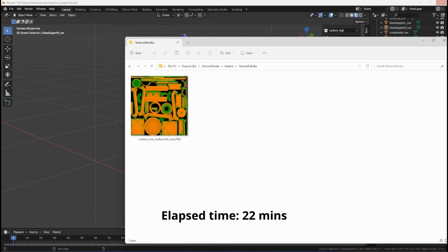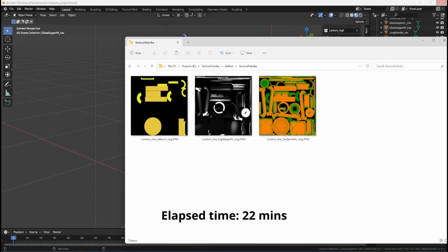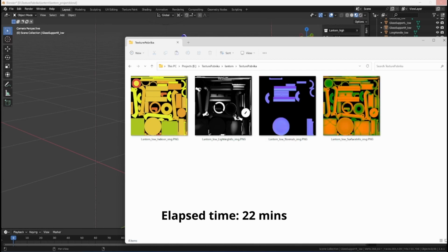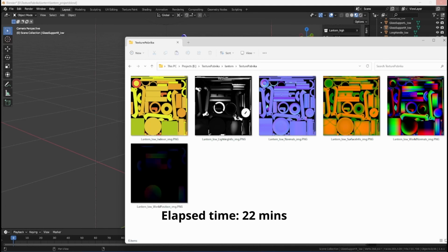Now, I think it's worth knowing that Texture Paprika generates a lot of stuff like view layers and shader nodes during the bake process. So if for some reason it gets interrupted, you might end up with some data on your file that you might not recognize. In that case, you might want to try and clean up all of these files, but the best thing to do would be to take note of what caused the issue. Reopen a previously saved file, that way you're sure you're working with a clean working file, and then fix whatever it was that caused the issue.